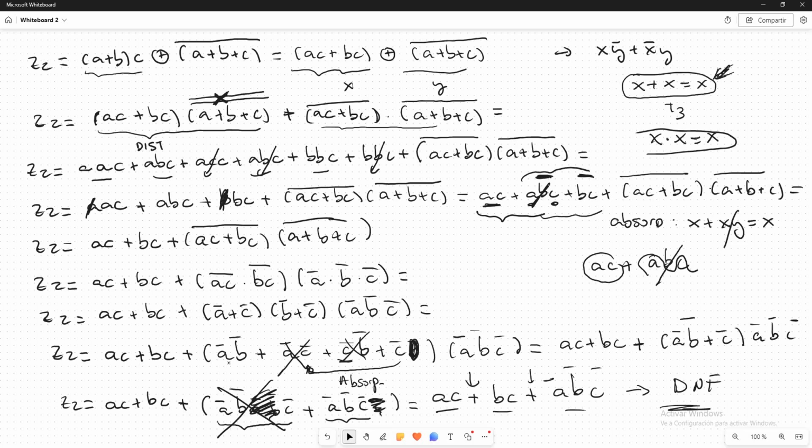Well, the starting expression was complex, so we have done a lot of calculations, but you can see that we can always reach the disjunctive normal form just manipulating a function algebraically. With this, we can build an OR implementation with logic gates, or an AND implementation negating twice. Remember what we have just seen.